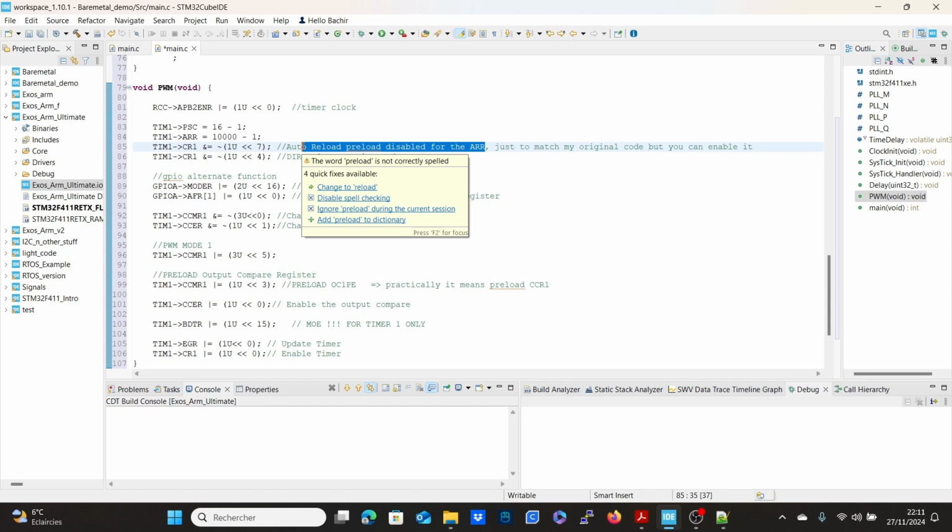What was going on will finish, and after the event, which can be an overflow, an underflow, or something like that, the update is going to take place. And if you don't have the preloading enabled, the change is going to be immediate with whatever consequences come with that.